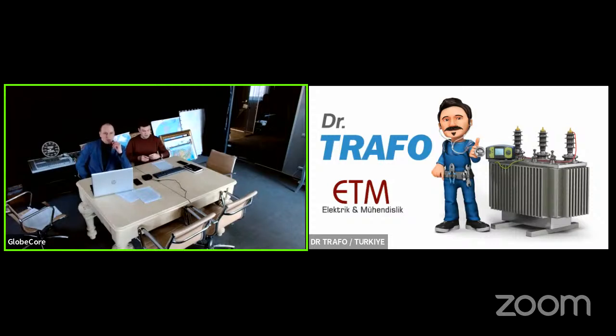Online regeneration. We cannot reply to your question right now because we need from you some very important parameters like oil testing results, acidity level, neutralization factor, BDV of the oil, moisture content, and so on. Only then can we calculate what the capacity of the unit should be to provide all your requirements. So if you need any particular project or case, it is better to discuss all the technical questions, fill in the questionnaire, and then our engineers will advise the best solution for your specific project.